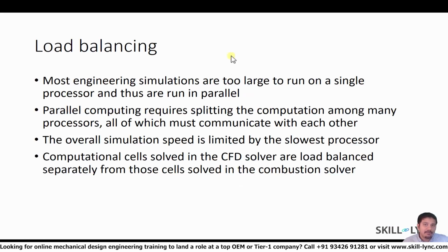The next important thing that we are going to be talking about is running simulations in parallel. Now, for the few simulations that you've already run, you might have used something called MPI run, correct? What is that? Well, first of all, CONVERGE is a parallel solver, which means it uses MPI libraries to parallelize different parts of its code so that it will run in different processes and across even different systems. Why do you need to do this?